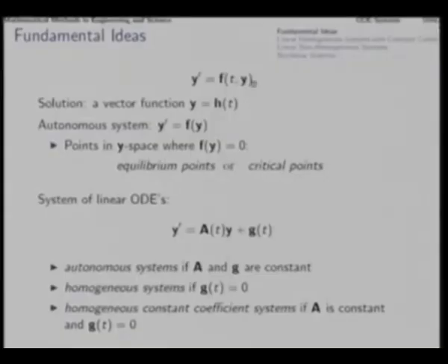And then we truncate the Taylor series. That gives us the first order representation of the same dynamic system, and the resulting differential equation turns out to be in this form, and then we can analyze that, and the result of that analysis will be valid in the immediate neighborhood of that particular reference point y0.